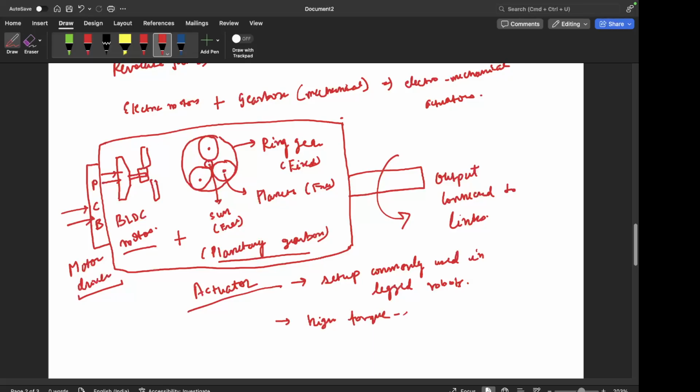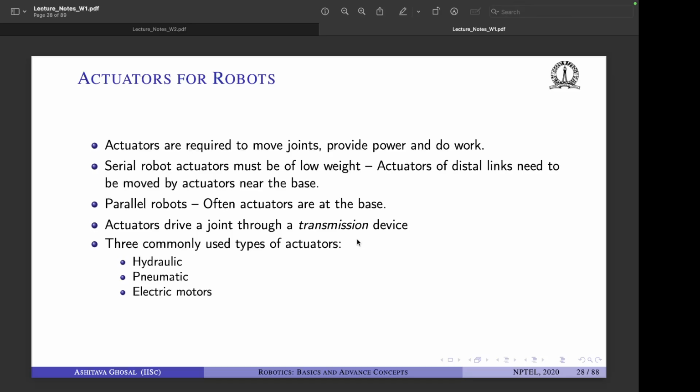torque to mass ratio. So torque to mass ratio is basically how much torque I am getting at the output, how much, let's say, peak torque can I get at the output, and what's the total mass of this actuator. So a higher torque to mass ratio implies that in a smaller mass, I can generate a lot of torque, and that always is beneficial because I can do different kinds of motions while also keeping my entire system lightweight, right? So that is one example.